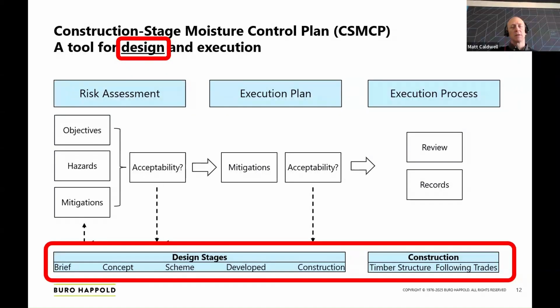And this is not just construction stage moisture, but ultimately moisture in use. So does it have a fall? That might be something that is baked into the design at a very early stage, so it needs consideration at that early stage. So it's a tool for guiding the design. It doesn't necessarily need to constrain the design, but it helps to raise the important issues nice and early.